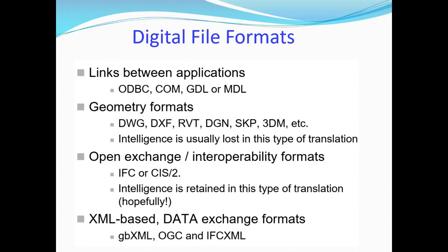Then IFC may not be able to understand it, because some software vendors want to give users more flexibility, so they allow custom objects that are understandable only by their platform. It's not IFC format, so some custom objects may not be readable by other IFC readers.